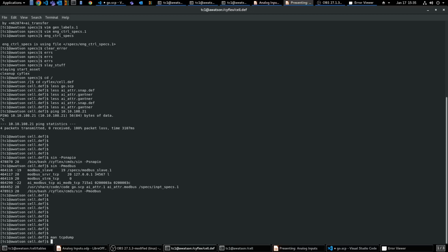And so that's going to weed out all of the traffic. Then I'm just going to stream that traffic, and what I'm looking for is, are the values changing? It's going to be coming through as hex. A lot of it isn't going to make sense, but it doesn't matter. What you're trying to see is, are the values changing? If the values aren't changing at all, then the device isn't streaming fresh values, and maybe you need to go into that device using the manufacturer's control software and reconfigure it.